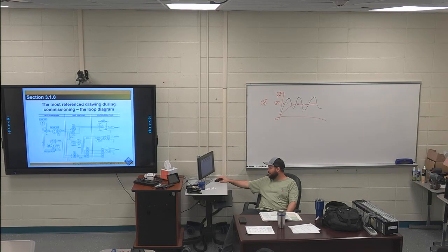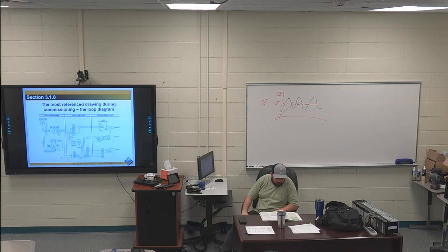Then you can see the actual loops going out from 10 and 9 to a pressure transducer that measures 60 to 200 inches of water, right? And then you've also got signals going in, like the signals coming from the panel junction terminal block 4 are controlling that air operated valve down here. But that's a loop diagram.